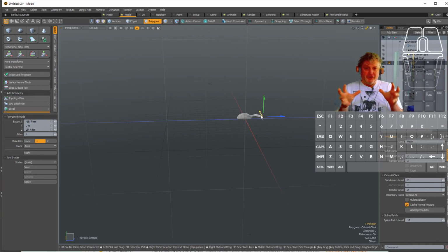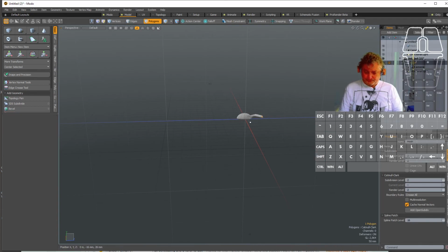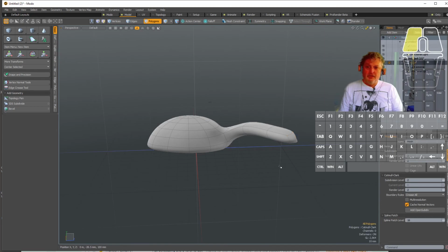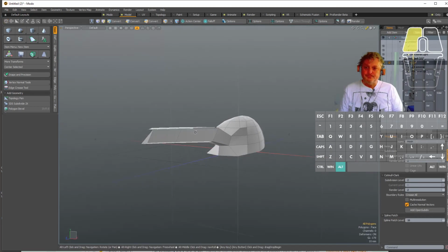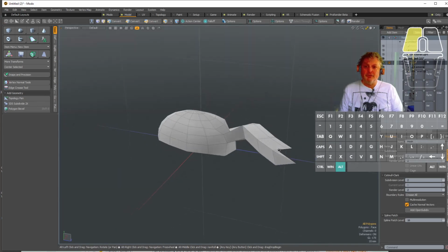We looked at bridging, which is how you can take two meshes, the polygons are facing each other, and attach them, or if you take polygons that are facing out, it'll make a tunnel. We looked at extruding, which lets us push out points, edges, and polygons, and we looked at the Shift Tab Subdivided mode. If I go back in here, hit the A key, deselect, and I hit Shift and Tab, that's my actual model. See very few polygons.